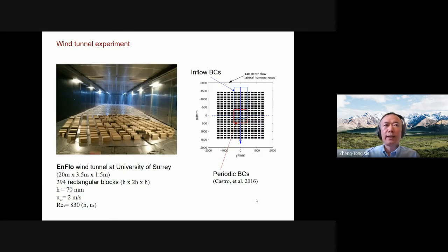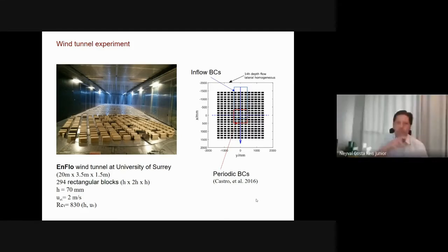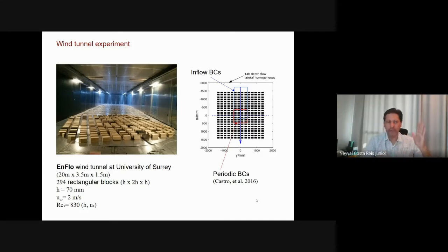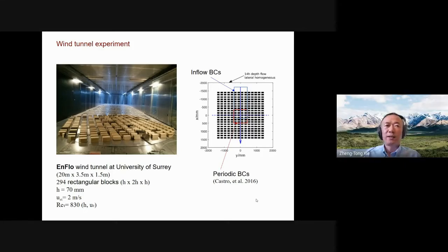If you want a good prediction of temperature, we published a paper with Victor. If you want a good prediction of the flux on the surface of buildings, you need a very high resolution. In the simulations you specify the temperature on the ground, and the ground and buildings are considered isolated. So you have only the stratification that is coming from the inlet, only from the inlet.